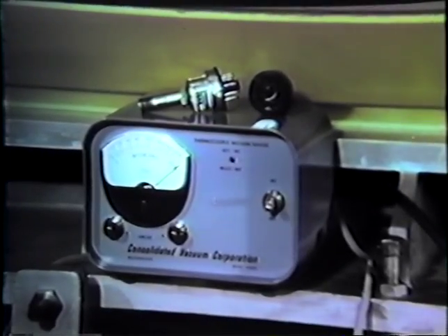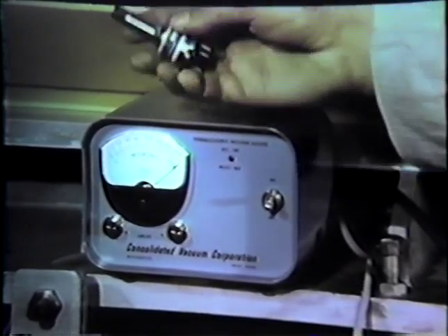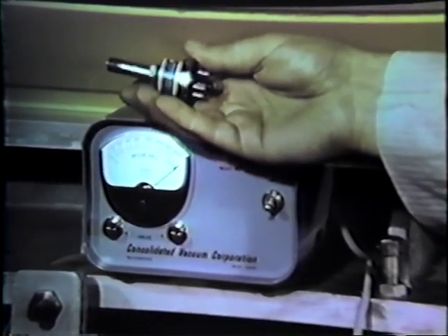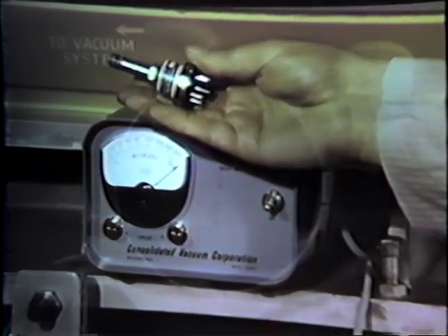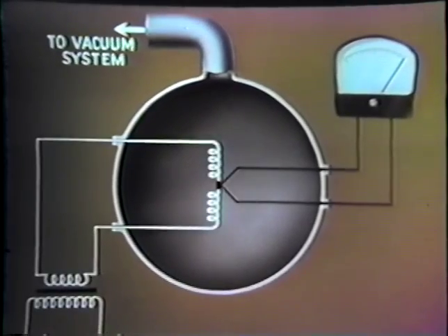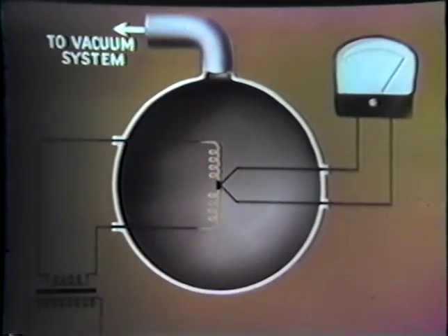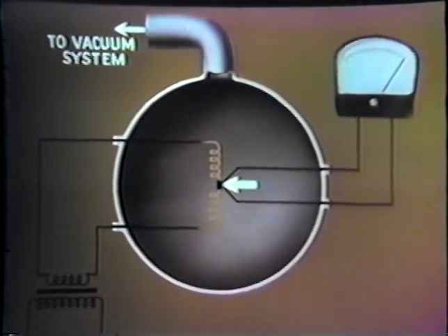The most commonly used vacuum gauges are of the thermal response type, one of which is the thermocouple gauge. Inside a bulb connected to the vacuum system, a constant regulated current is passed through a wire. The temperature of this wire is accurately determined by a thermojunction affixed to it.